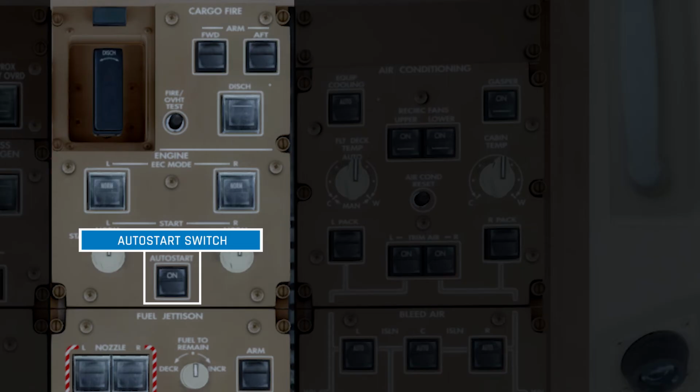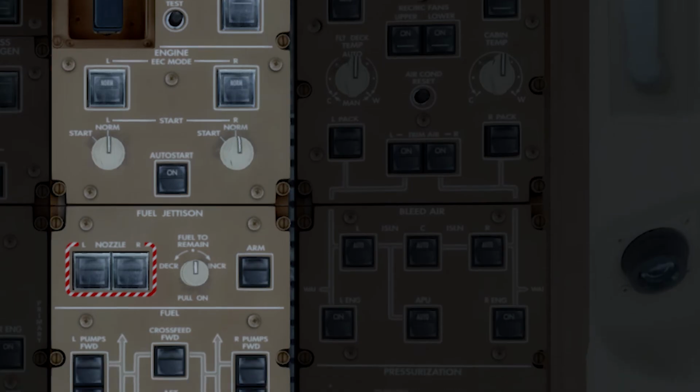Now when this process begins, the engine gains rotational speed until it reaches its idle speed. In older aircraft, you would manually wait for the bleed air to rotate the engine to a particular speed before you would introduce the fuel. Now for anyone who's flown a Boeing 737, you know exactly what I mean. In the Boeing 777, the auto start system automatically monitors the engine speed and will automatically introduce fuel to the engine at the correct time.